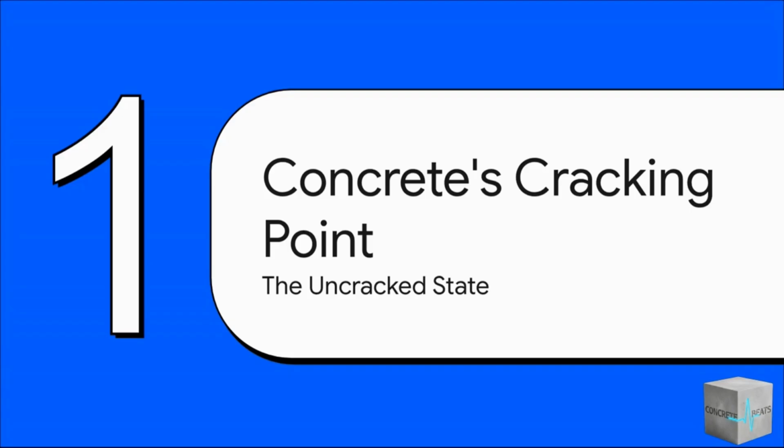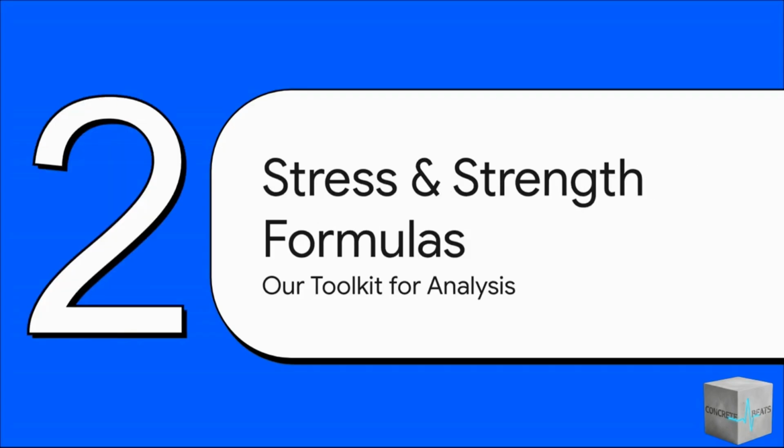So you know how concrete beams have all that steel rebar inside? Well, for a while that steel is just hanging out. It's not doing anything yet. The beam is acting like one solid block of concrete. Our mission, really, is to figure out the exact limit of that state. You know, the precise moment the tension gets to be too much and the concrete just can't take it anymore on its own. Now, finding this cracking point isn't guesswork.